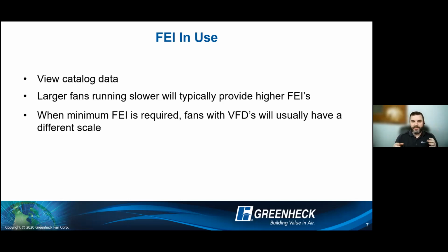This is because in the FEI, the way you calculate it, and there's an entire long calculation testing the whole works, if you apply a VFD, you actually take a slight hit to your FEI numbers, but then you gain that back by being efficient operating in a zone, okay? But because of that hit, many times you will see two different scales, something to watch out for.